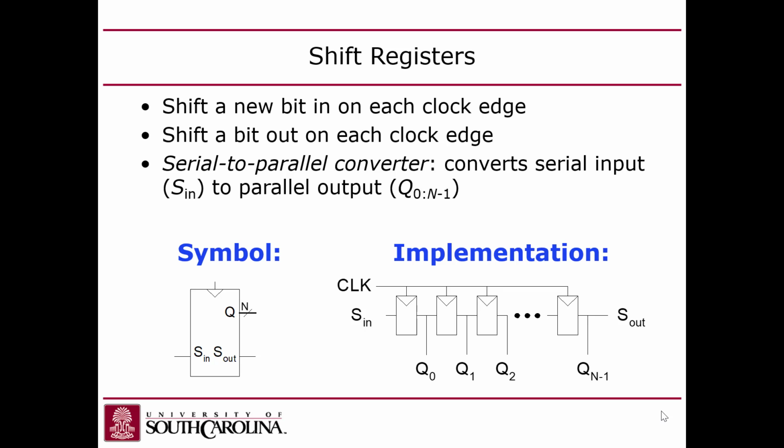Yes? So in theory, if you slowed the clock down far enough, would it have the potential to propagate more than one? No, these are edge triggered, so you'd have to extend the rise time of the clock. Normally the rise time is like 1/10 of the clock period or less. You'd have to make the rise time stupid long. Yeah, to make that happen.